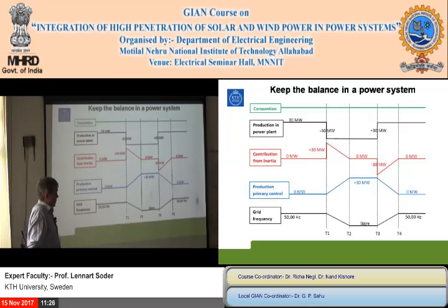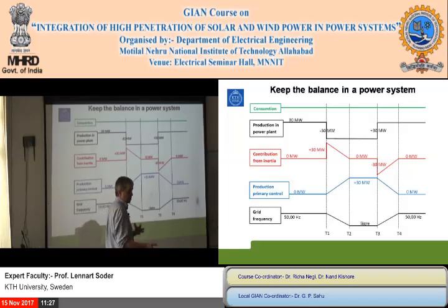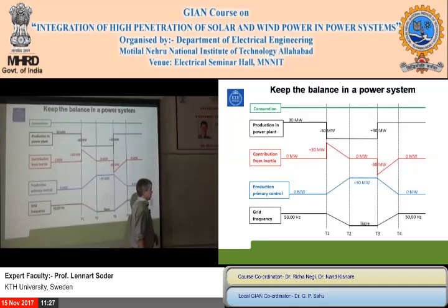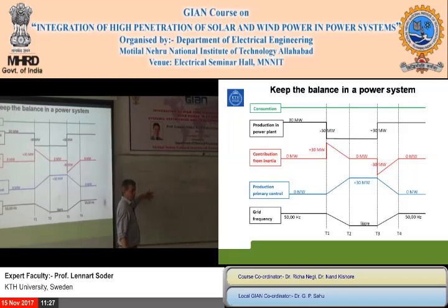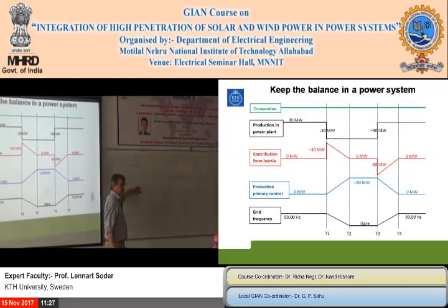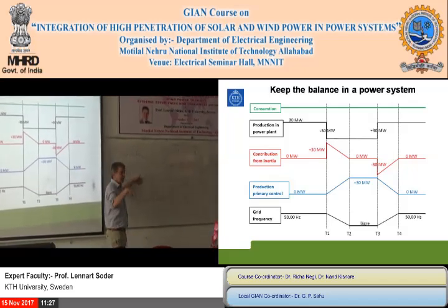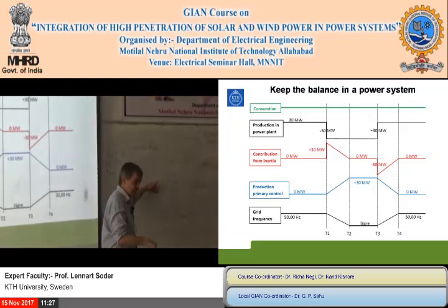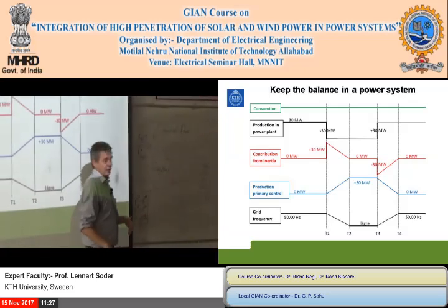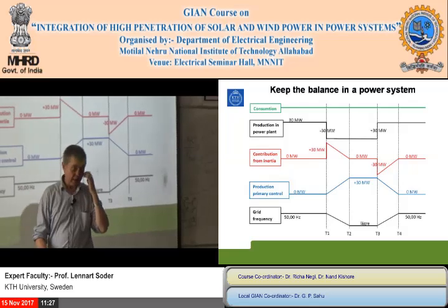There are then some challenges if you have wind power. Where is the inertia? Because this is really the big fundamental issue. This whole control system, that means the power system working, is based on having inertia in this kind of power plant. What is happening is, of course, that if these don't exist, or you have very few of them, then the frequency, when something happens in the system, and that is one of the challenges that is very much discussed today, how to handle that.